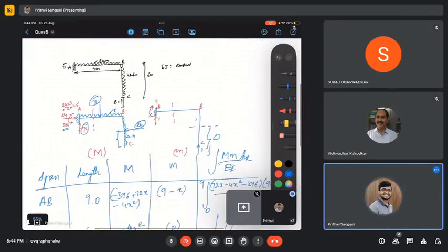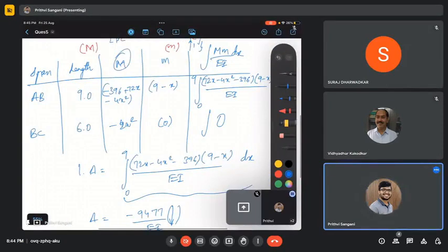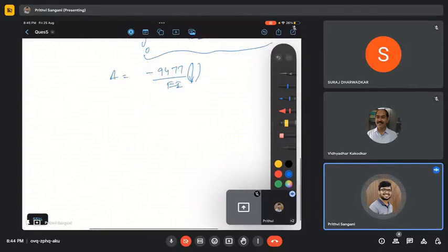Let us also find the horizontal displacement, or horizontal deflection, at C. For the same question, let us also find the horizontal displacement. Delta H is how much? So my capital M will be the same. There's no change in it. Only the small m changes.